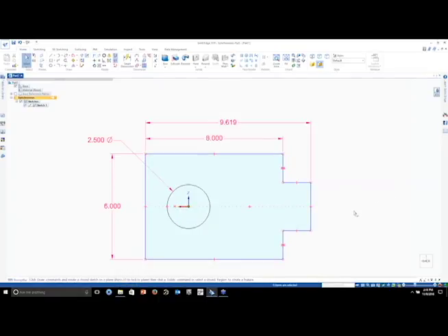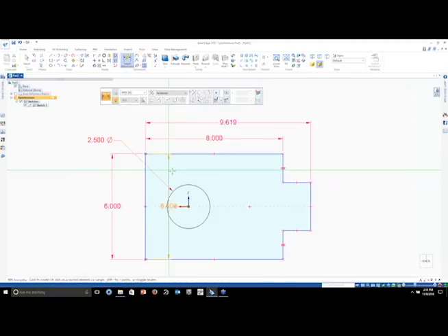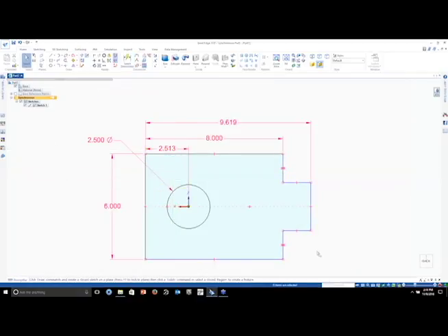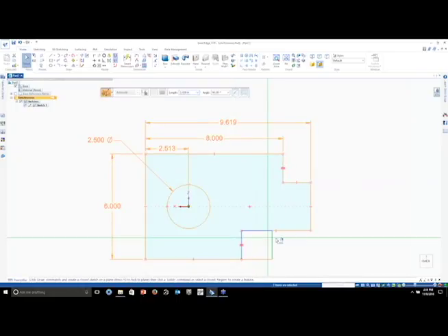You notice it drags off the coordinate system because it's not fully attached. So I'm going to use another relationship. I'm going to make sure that's attached by using a connect. All right, so I'm just going to say connect center to endpoint, and you notice something different. My profile turns black. So that circle is being located by a relationship, and it's also being dictated 2.5-inch diameter.